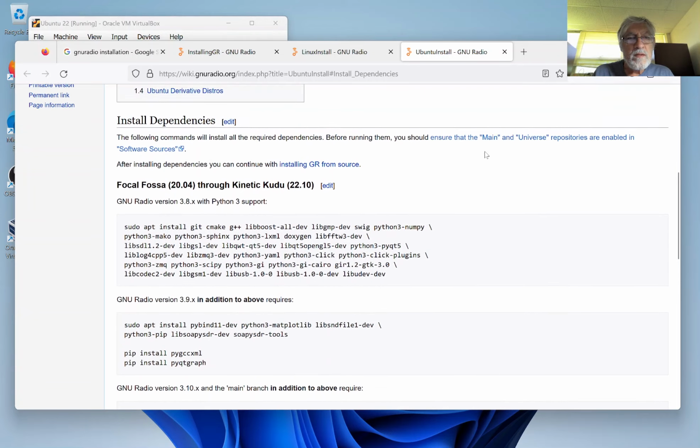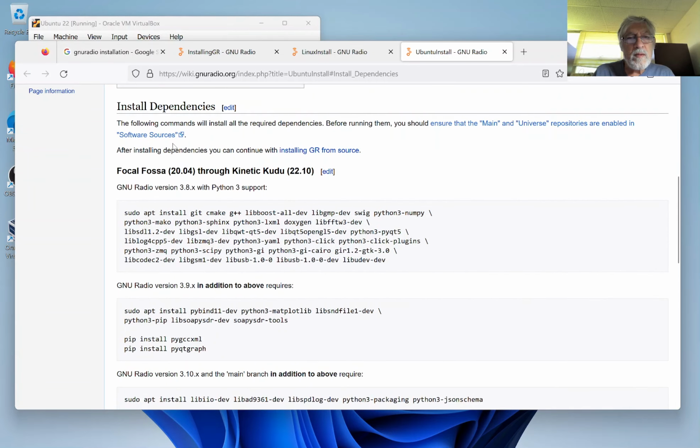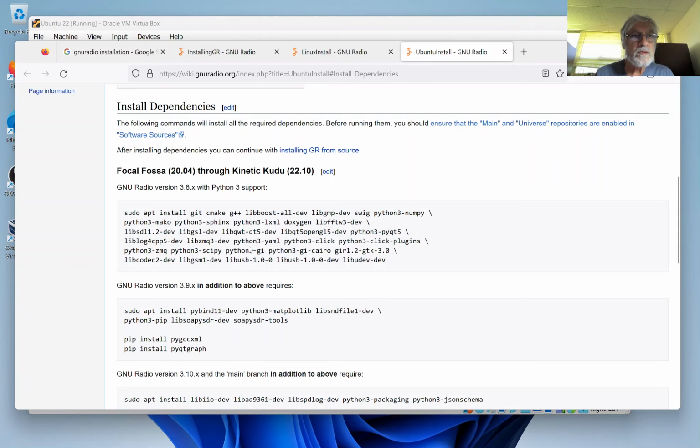And it shows you the kind of programs that you have to have installed for GNURadio even wanting to be installed. So what we will do is we will take a copy of those and we will just bring it over to our virtual machine and then install those things first, and then we will do the UHD installation, followed by the Volk and the GNURadio installations.